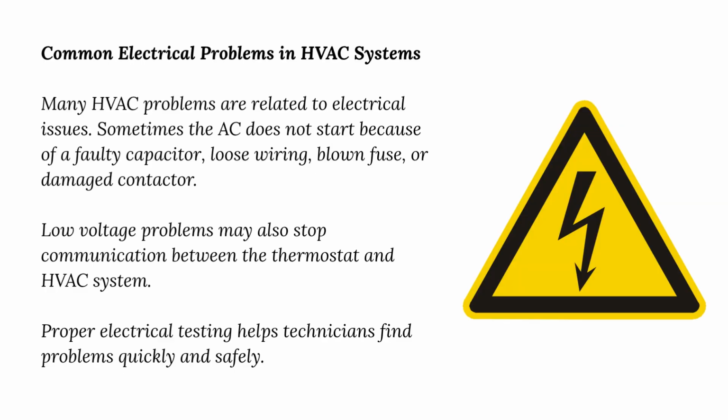Common electrical problems in HVAC systems. Many HVAC problems are related to electrical issues. Sometimes, the AC does not start because of a faulty capacitor, loose wiring, blown fuse, or damaged contactor. Low voltage problems may also stop communication between the thermostat and HVAC system. Proper electrical testing helps technicians find problems quickly and safely.